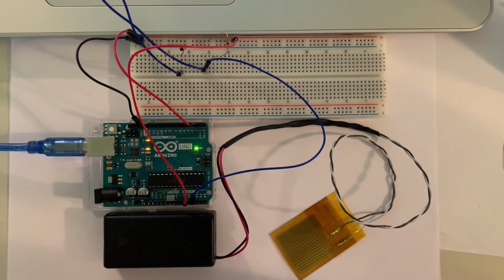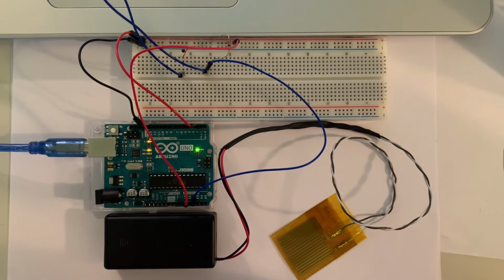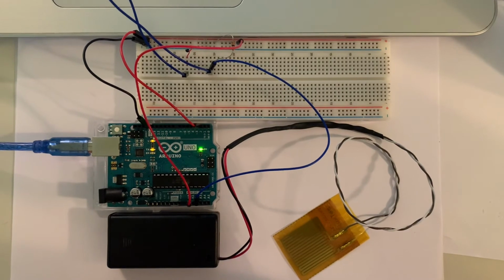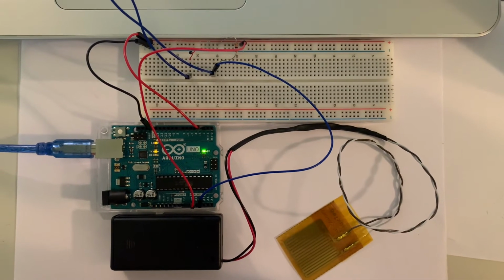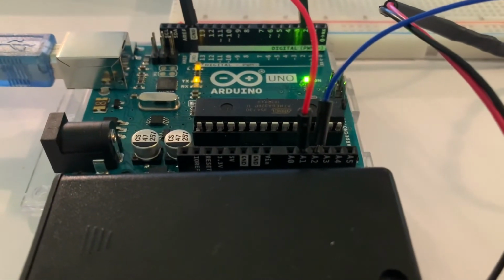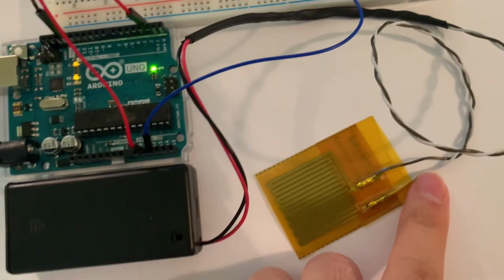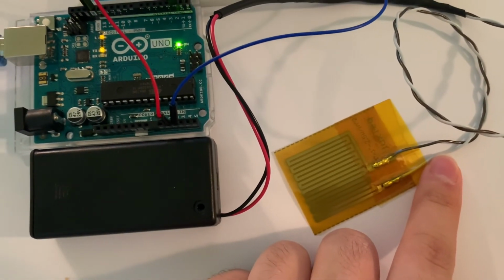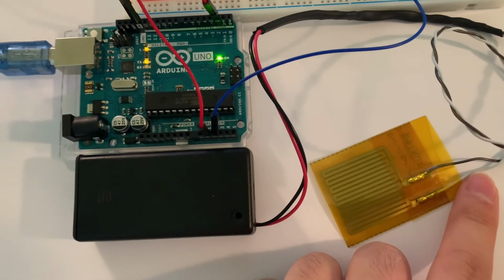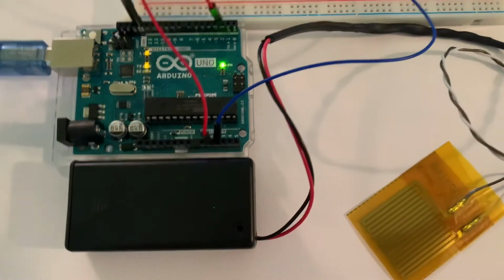Here is my voltage divider circuit. I am using the 10 kiloohm resistor and thermistor. Additionally, I am using analog pin A2 to read the output voltage. To heat my thermistor, I am using this thin films heater as well as my finger. Additionally, I have changed my baud rates to 9600 in both my Arduino and processing code.